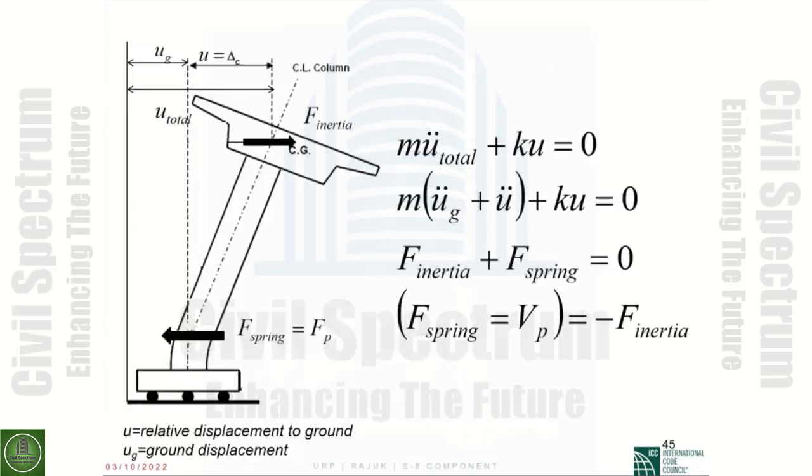This is here where you see the seismic forces and where you see the limit on the seismic forces regardless of where is the inertia force, because V sub P will be the plastic shear on the column regardless of what the inertia force will be, or regardless of what the ground motion will be. So that limit is V sub P, regardless of the magnitude of the earthquake. But as I said before, bigger earthquakes will give you larger displacement.